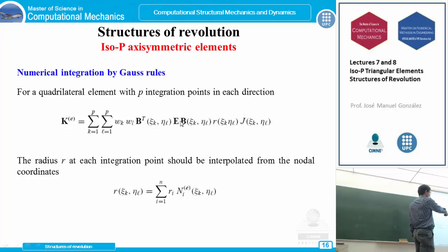Your B matrix here, which involves this shape function divided by r. Okay, and which r are you calculating? Well, the location of your point comes here. So you are calculating this expression at the integration point. So if this integration point is placed on the axis, you will have an r equal to 0. So the solution for this problem is to use an open quadrature, which places the Gauss integration points not on the boundaries, but in the interior. Okay?